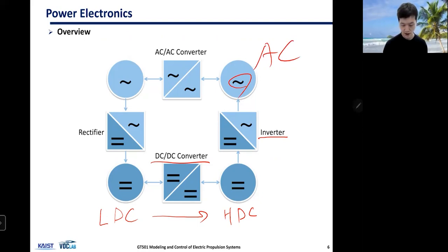And you may have, for example, if you are using motor as a generator, then you have AC signal coming in to your converter, and you will need to convert your AC signal into DC battery power source, and you would need rectifier to rectify, make AC signal flat so that the battery takes constant voltage.